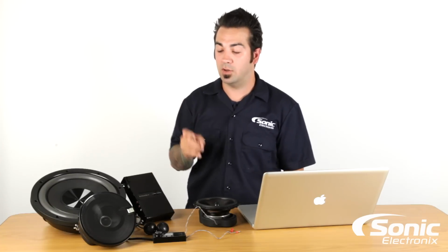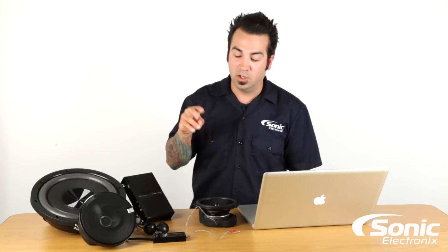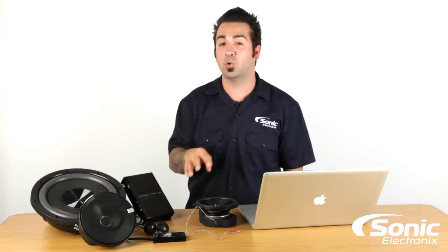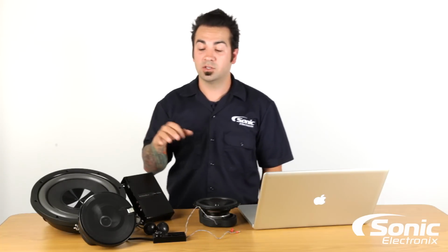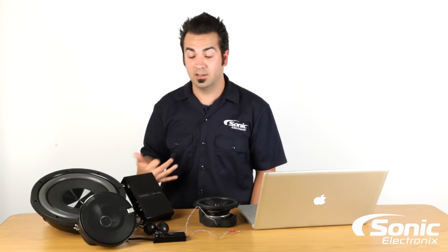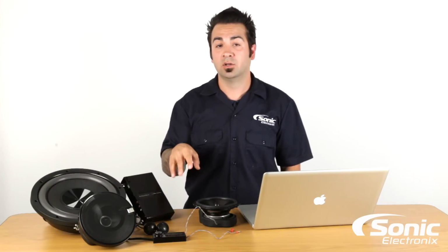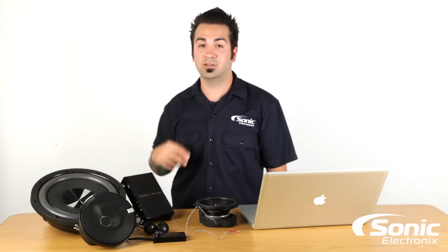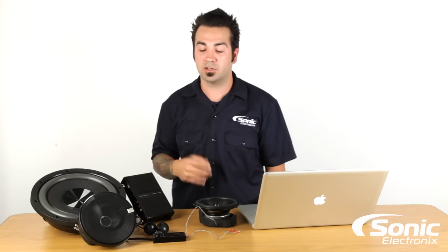So I thought that was really cool. So it's not completely limiting you. However, having said that, you cannot buy, and it does not support, additional tweeters. So if I had a vehicle with 2 sets of components in the front, components in the back, I don't have the ability to buy another set of tweeters. You can't. There's not enough outputs on this Z3 brain to support additional tweeters.